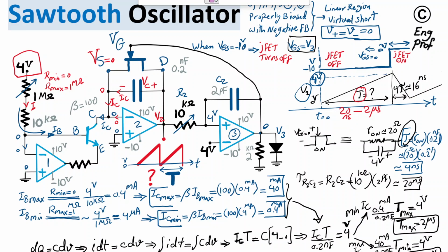So effectively, what I'm saying is, instead of a sawtooth in that case, we are getting into a triangular waveform, because the drop or downside roughly matches the upside. So it becomes more of a triangular wave roughly. Alright, so we need to be careful about that, but basically we know the big picture. We can adjust components in the circuit so that, at whatever range of T, we improve the look of the waveform.